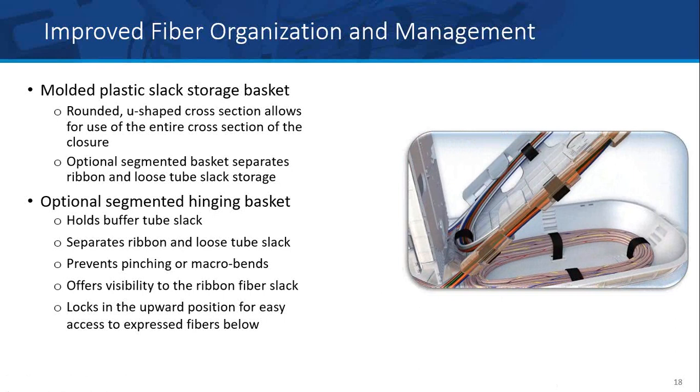When I press this back down, it locks into place at that 45. I can press this down and lock it into place, and I can make sure when I press this down, I'm not grabbing any fibers or pinching anything. Make sure that you're clean down below before you close the splice closure up and move on to the next one. And it's also hinging to allow you to access the bottom, to access those fibers underneath.